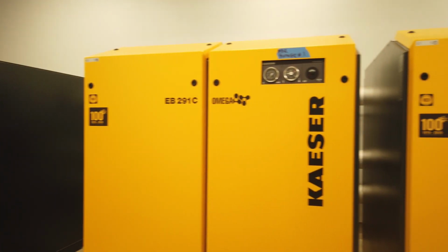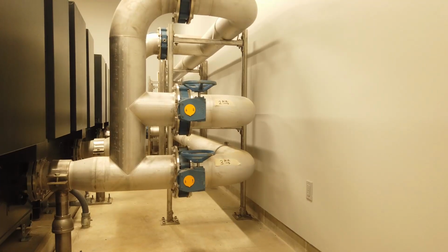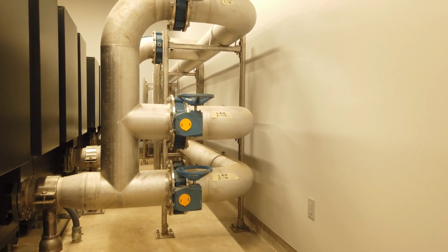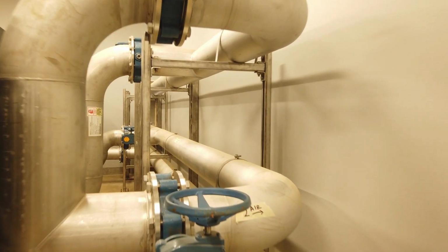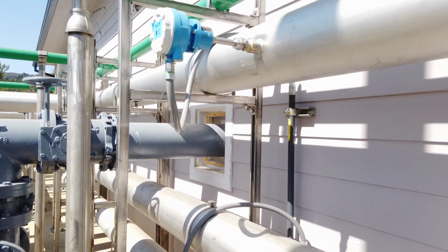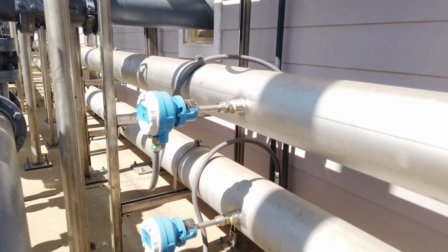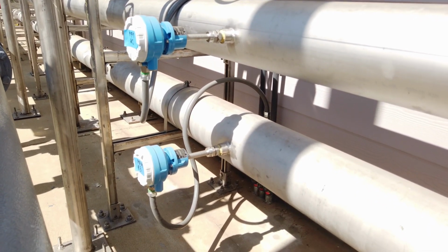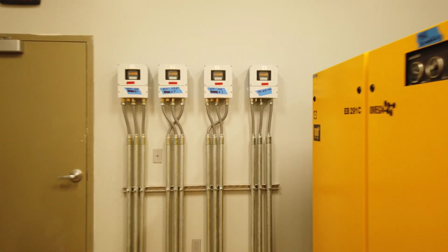There are 4 blowers, one for each MBR tank and one for standby. The blower piping was designed to allow the standby blower to deliver air to any MBR tank. The MBR blowers each have flow sensors to manage airflow to the MBR tanks. All of the blowers are rotary lobe type, also with a considerable turn-down ability.